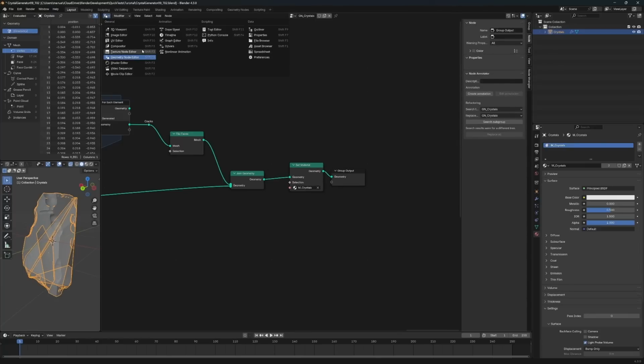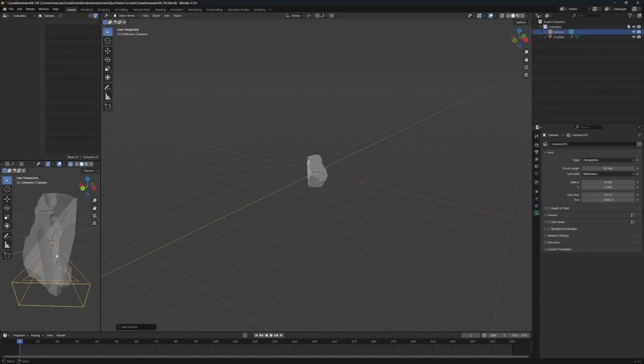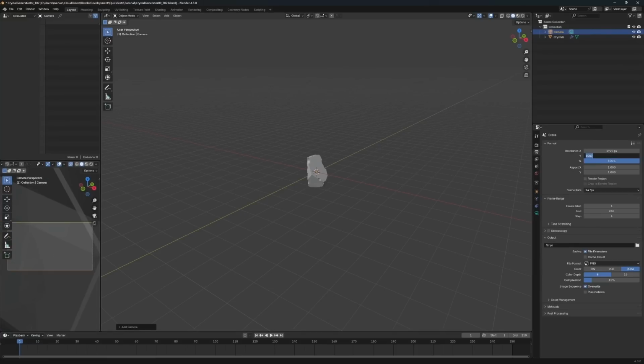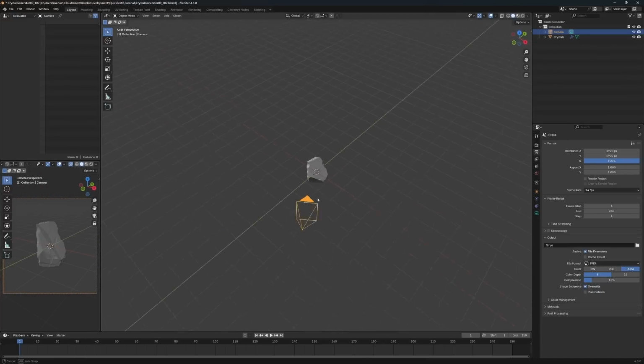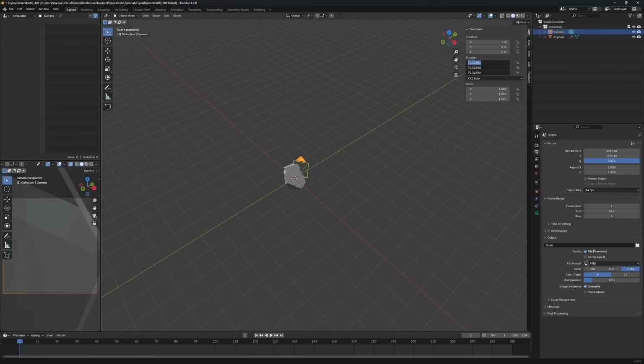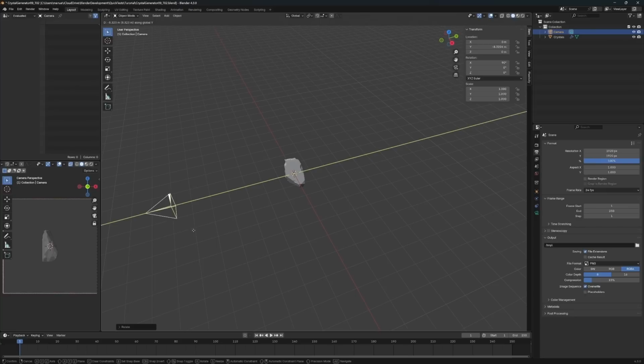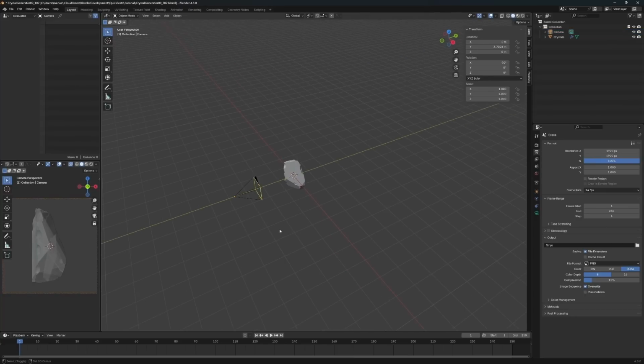Now for shading the crystal, I quickly switch to the 3D viewport here. Let's first create a camera and let's look through the camera over here. I switch my resolution to 1920 by 1920 to have a square camera and lock the camera here, move out a little like this. But I want to place the camera using values, so go to 0 and 0 rotation, and then I want to rotate along X by 90 degrees and move the entire thing back in Y, like so.